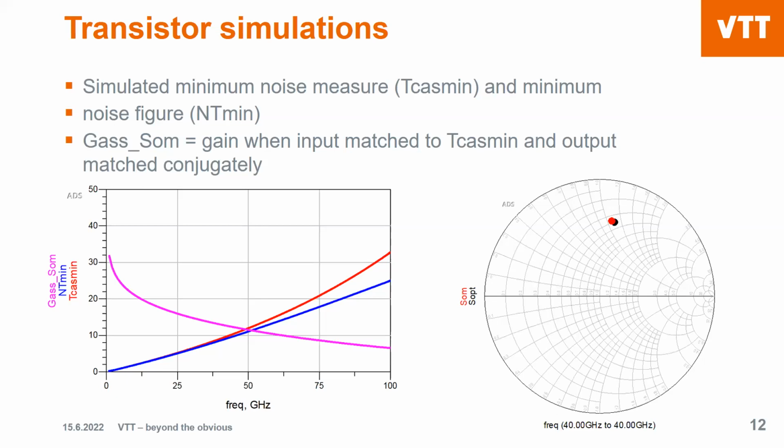What is the impedance that will give you the optimum? It's the red one. One is in the cascaded case, and the other one is the intrinsic, the case where you would match only one transistor. So this is for the input in particular? Input, yes. This is the impedance that the transistor wants to see at the gate.